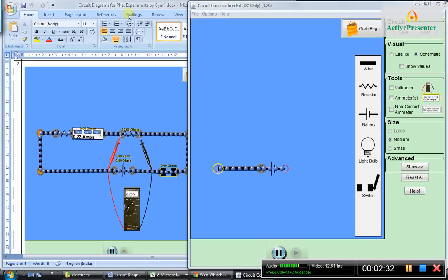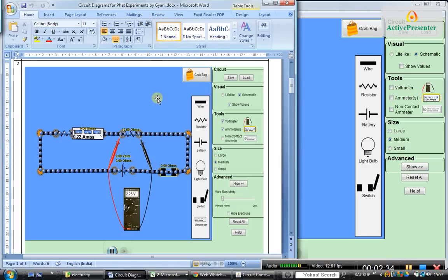Okay, before I continue, my students who are sitting with me had again some confusion about why we need this other resistance here. So let me explain that point in more detail. See here, the goal of this experiment is to find out what effect current has on this resistance, in the sense that there is some potential difference across this resistance. How does that potential difference change if we change the current passing through this resistance? Now imagine that you don't have this first resistance, you have only this 10 ohm resistance and this battery. Then the current passing through this 10 ohm resistance is fixed.